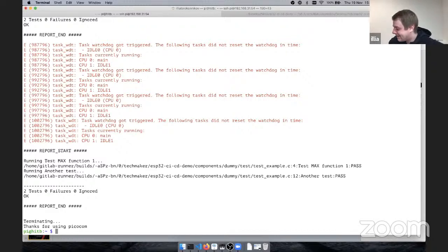And for the real embedded devices, you actually have no emulators at all, because you have plenty of other peripherals that you should emulate. This is the problem with peripherals too, because I think in 2019 somebody from Google shared some fuzzing for embedded devices. But that's a simple situation where you have to care only about the SoC that you're emulating. With the real hardware, it's a lot of peripherals, like buses, I2C, CAN, JTAG. These actually are cutting edge technologies right now. I mean SDR, like ChipWhisperer, these tools are actually made for fuzzing different peripherals, but not emulating them.